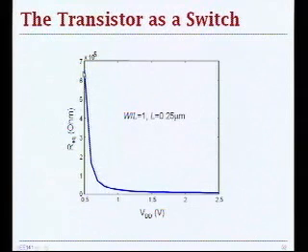These results are quite different if you decide to use a longer channel, and it's important just to understand the methodology and the way you can calibrate and calculate your equivalent resistance. So if you are given some other channel length or width, you can pretty much recompute this curve.